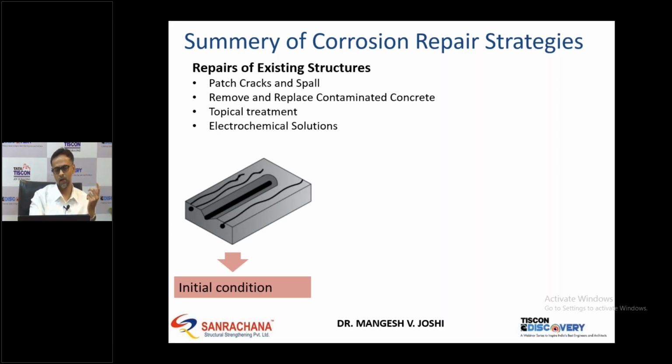So normally we come across this type of initial condition. These are the conditions where we see some minor surface cracks on the surface of the concrete, and that's when we come to know that there is some issue with my RCC and I need to treat it.